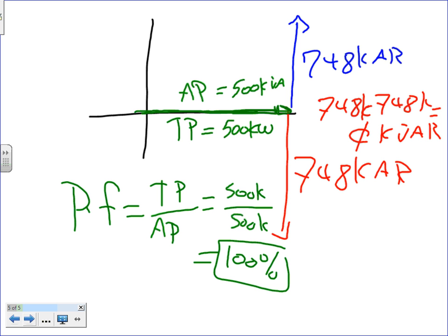Long story short, by adding more DC, they over-excite these motors. And these motors, instead of consuming kVAR as they should, when they over-excite them, they start giving kVAR in the opposite direction. Normally, the motor is supposed to consume the kVAR, so the kVAR is coming from the source into your motor. When they over-excite the synchronous motor and don't load it, they do the opposite. They flip it and start pumping kVAR. It's acting like a capacitor.